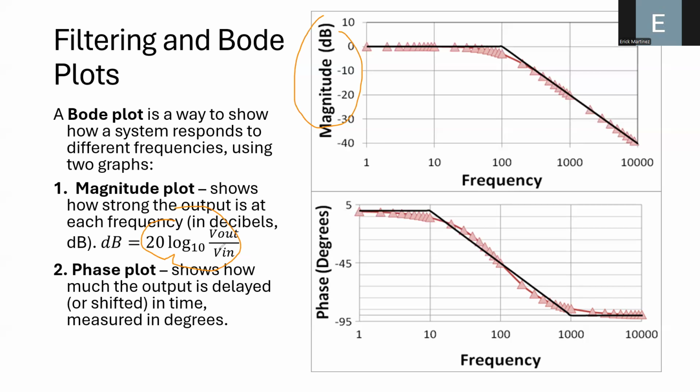Here we are relating the output with the input voltage. In an electronic filter, this output voltage will be your signal without noise or without certain frequency components, and the input voltage will be the signal that we're measuring directly from the sensor. So we are using this Bode diagram to know the frequency response of your circuit or your electronic filter, okay?